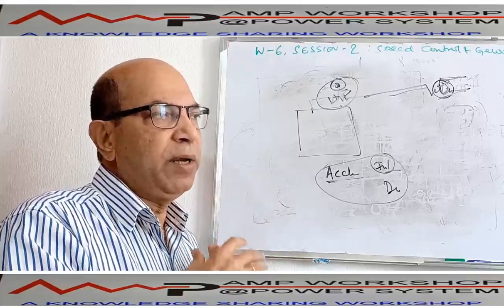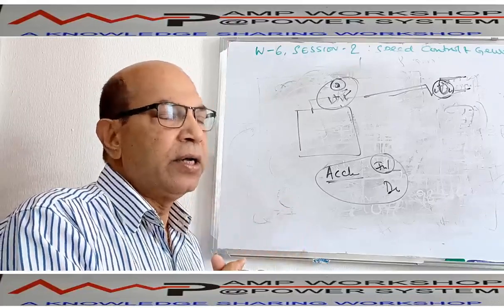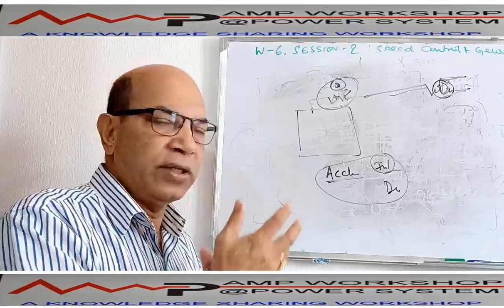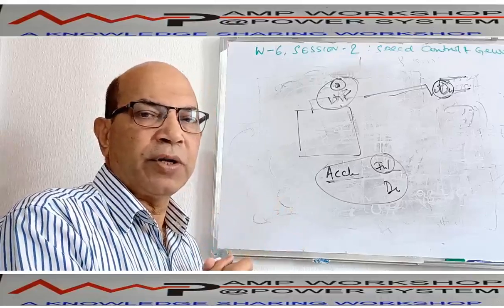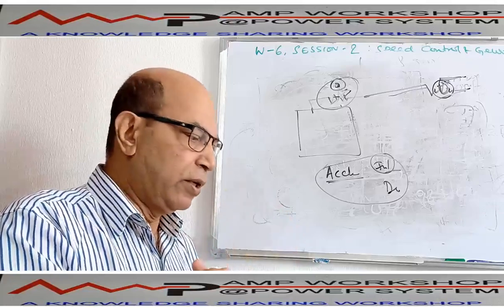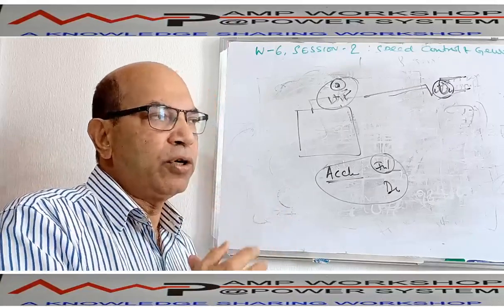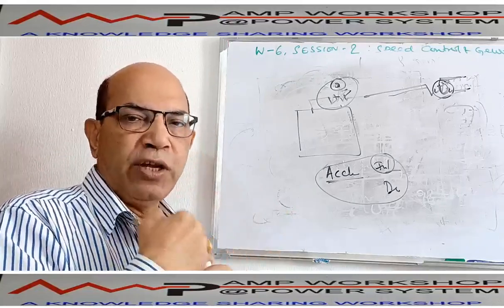Previously the governor was a hydraulic type. It could also be a mechanical governor. Nowadays all the governors are mainly electronic or digital governors, which are very fast in acting with a lot of setting provisions, and with governor operation we can make the machine speed or frequency stable. So this is all about the governor. Droop mode is slightly sluggish or delayed, but isochronous mode is very quick.